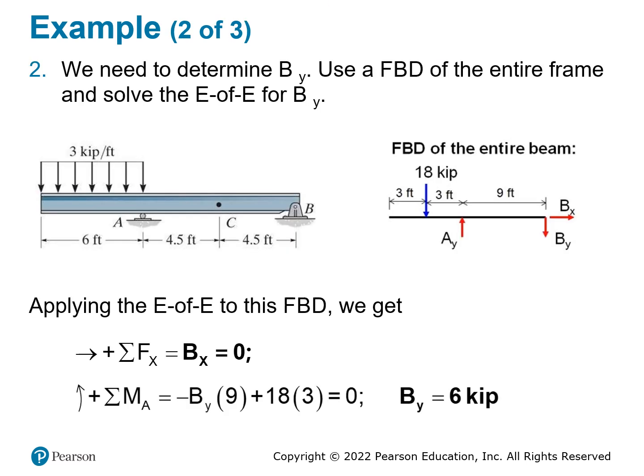So we put together the free body diagram from what we identified. We have this distributed load right here. We have AY here. We have BY and BX here. Now the direction is arbitrary. This one I made go down, but you need to know that this direction is arbitrary, and once you find a solution, the sign will tell you the correct direction of the load.